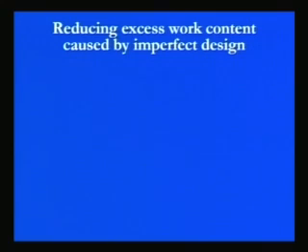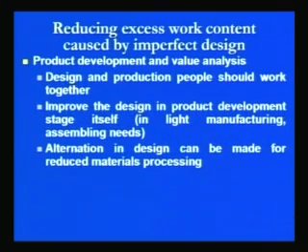Excess work content caused by the imperfect design of the product can be reduced by various approaches. Product development and value analysis is one of them, which basically involves that the design of the product is made perfect so that it allows use of the most economical manufacturing process. This becomes possible only if the production people and the design people work together in order to develop the design of the product in such a way that it permits the use of the most efficient and economical manufacturing process.